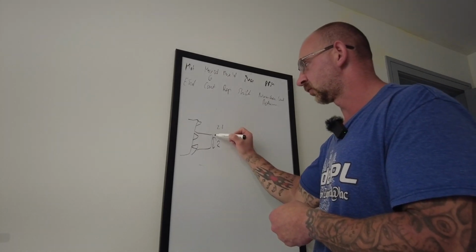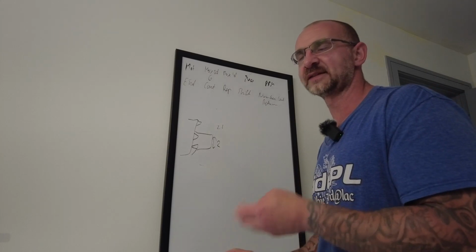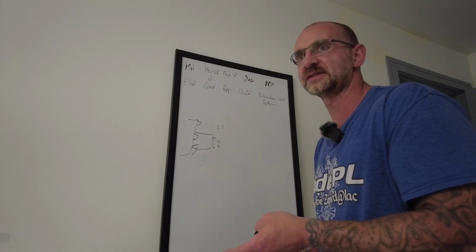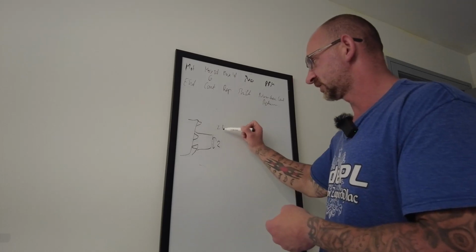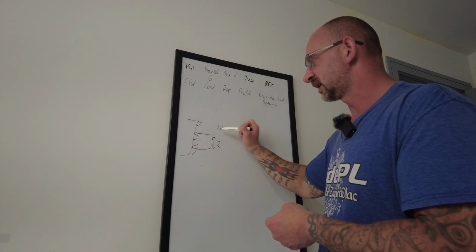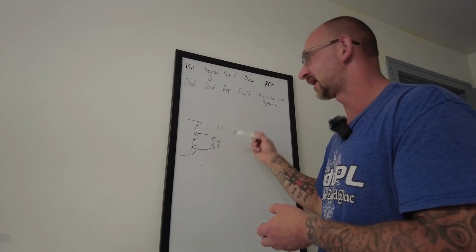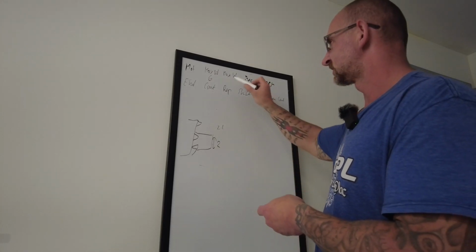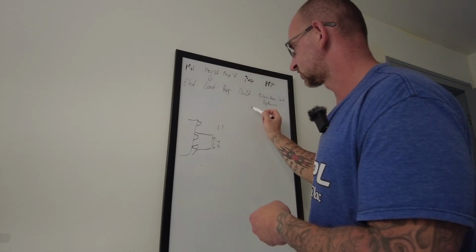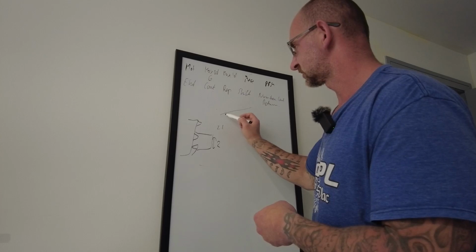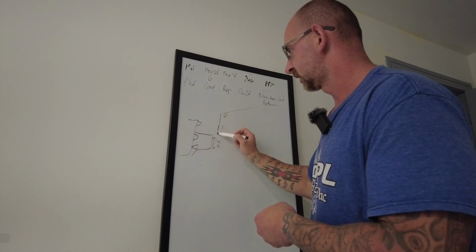Sometimes you have 10 parts and one part that's extra long, so it doesn't come in and just shove into the material. So I start at 2.1, and if I see it's trying to remove too much material, I have time to stop it. On a 2-inch part, like I said, it's just going to come here, stop at 6 inches, then drop to 2.1, okay?